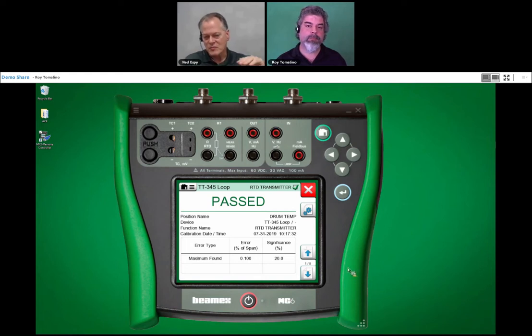But if you're seeing 20% today, you go out 6 months from now, it's at 40%, you leave it alone. You go out a third time, now it's at 60%. Now you've got kind of a documented trend going on. And so not adjusting is a good thing. So Beamex presents this term significance to help you make a good decision for how you're wanting to work.